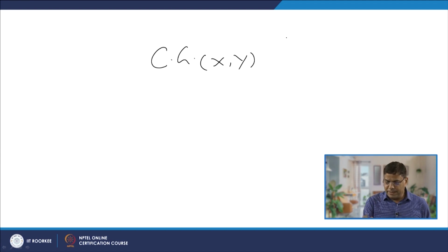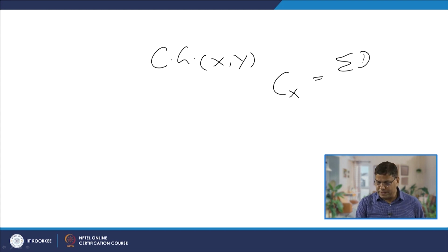So, the center of gravity x coordinate, Cx, is identified through the algebraic sum of the distance to be travelled from the different points on the x axis multiplied by the corresponding weight, divided by the sum of all these weights, that is the load.